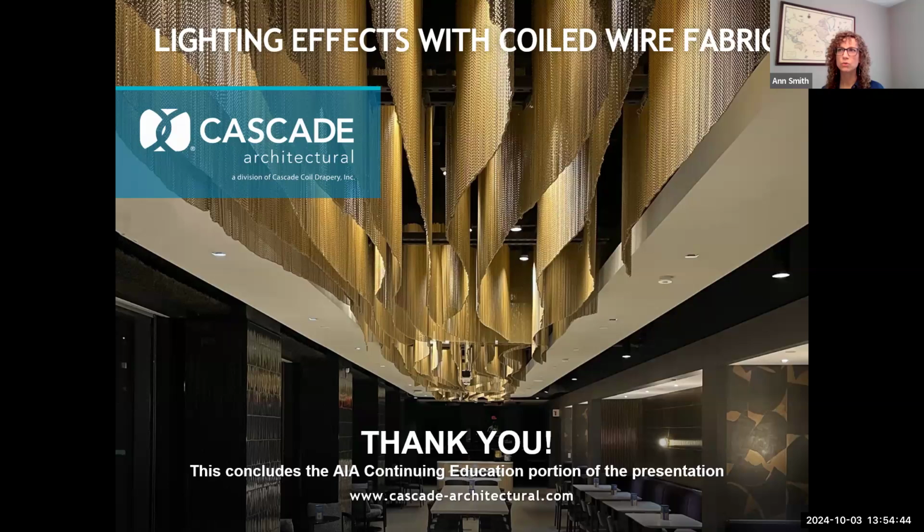With ice and snow, we many times will calculate it as if it were a sheet as far as the attachments being able to support it. The reality is, because it's textured and open, it's never going to create a scenario where, like with glass, sometimes it can gather onto that and then maybe slide off and become a danger to people around it. It usually will melt, and so it doesn't really gather the ice and snow like other products might.